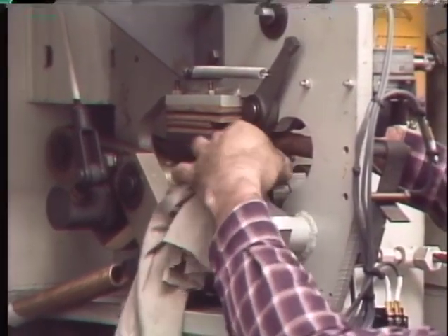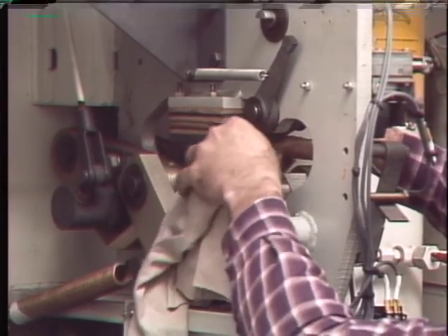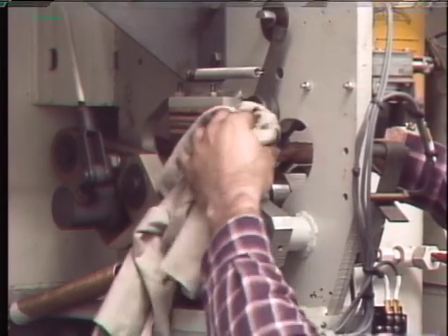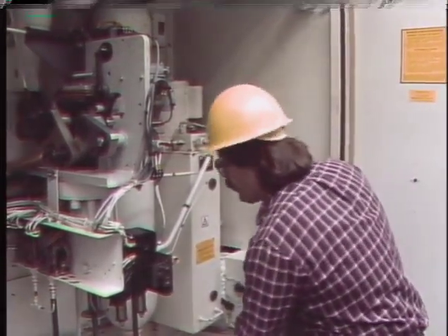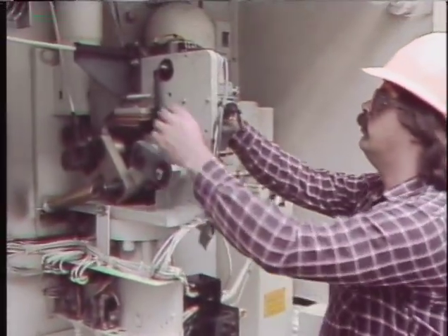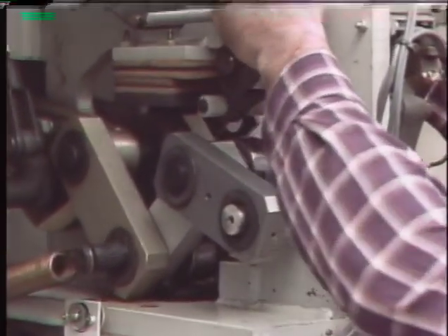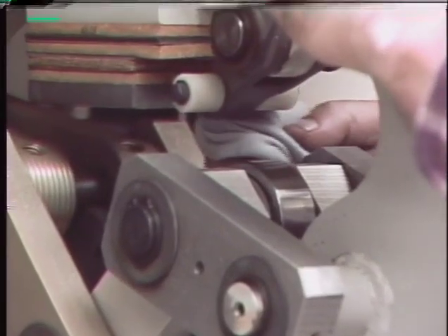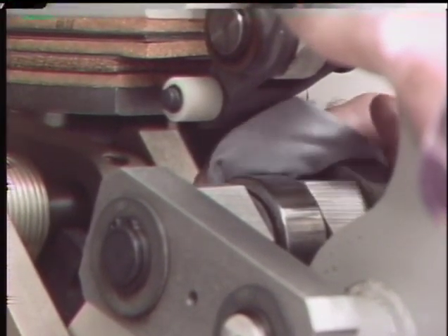So it's a good practice to wipe off the links, levers, control coils, latches, rollers, and other mechanism parts. Dirt or rust can be cleaned with a solvent if necessary, and a small amount of rust inhibitor can be applied. While cleaning the mechanisms, you can also inspect them. Signs of wearing may indicate that some lubrication is needed.